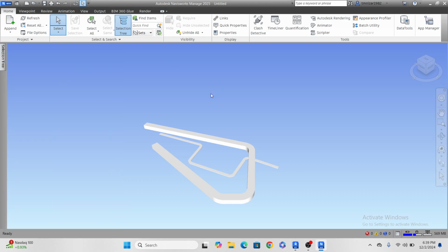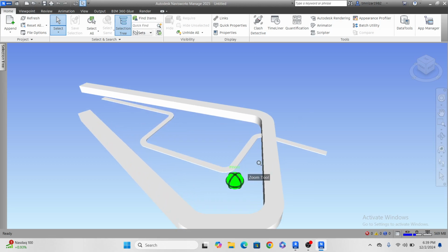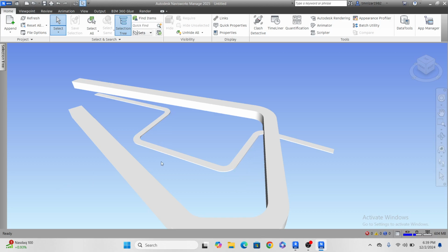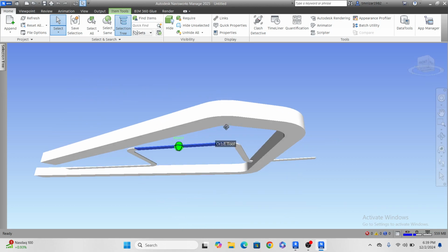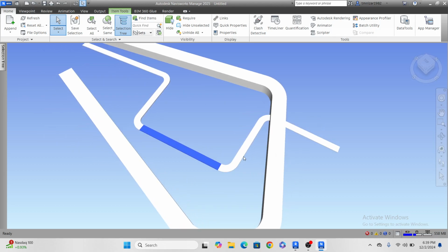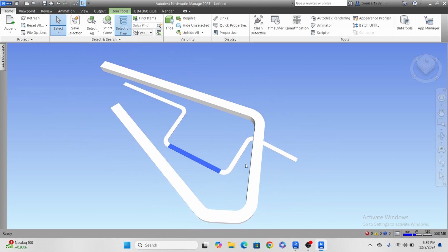Okay, now what I'm going to do, I am going to check whether this is clashing or not. When you're viewing, you can select any of these models, press control, also shift. Press shift and the center mouse button and click. Okay. You can see it's already clashing. But let's say you have a huge file. You will not know where it is clashing because it's a very, very huge file. So at that time we have to export each service separately like this and check the clashes.